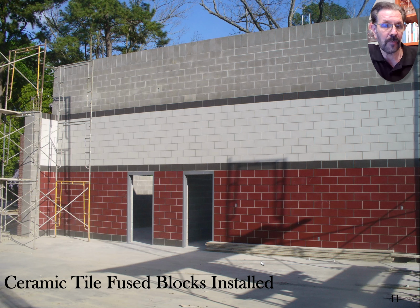The other thing over at the corner, they don't have a roof on here yet, but those columns that are right by the door, defining the door, in fact, they've got 16-inch by 16-inch blocks there with some heavy rebar inside them in concrete. Because if the fire truck hits that, it could be bad. So they made those things stronger so that even if a fire truck hits it, that sucker's going to stay up there.